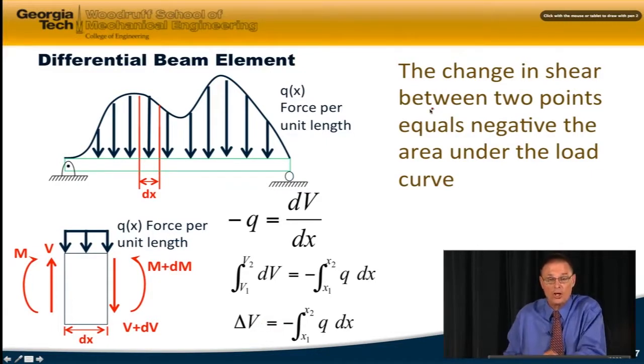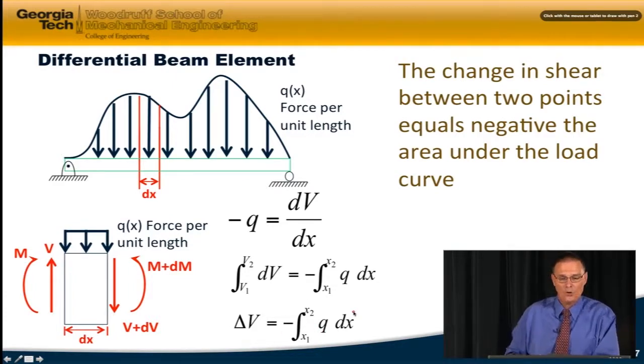The change in shear between two points equals negative the area under the load curve, which is represented by this integral. And so we'll use those two relationships as we draw shear force diagrams in future modules. And that's it for today's module.